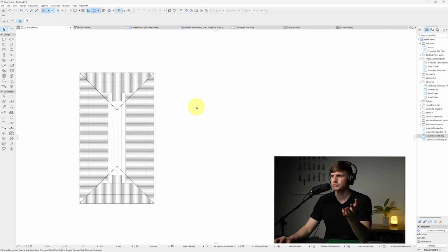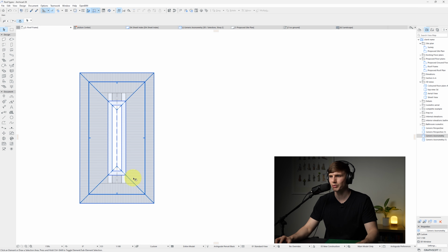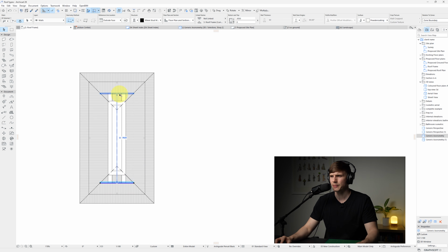This is showing where they've pasted those walls. We'll click outside and we can't currently see our walls. If we hover our mouse, they're quite difficult to find. If we hold in Shift while we hover our mouse, it's going to select through those different elements when we get to the edge of them. So if I hover over this edge just here and move it until we can find the edge of that wall, that's going to allow us to select these walls.